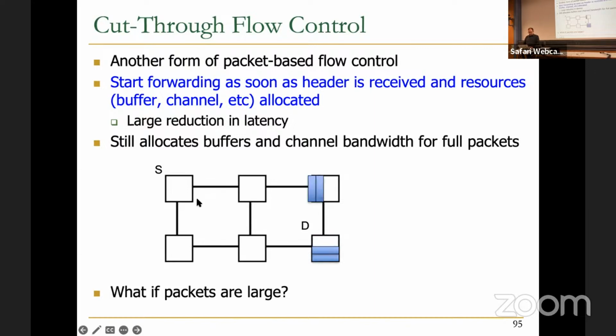So when the header is being sent to this node, we also do the routing for the next hop ahead of time, such that we are one step forward. And also, when you want to take the output channel, you can do it speculatively. You can speculatively assume that you're going to get the allocation slot, and that can provide much better latency. But at some point, yes, your speculation does not work and you need to wait, essentially.